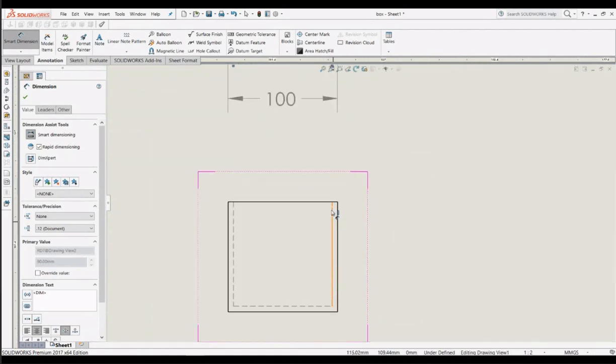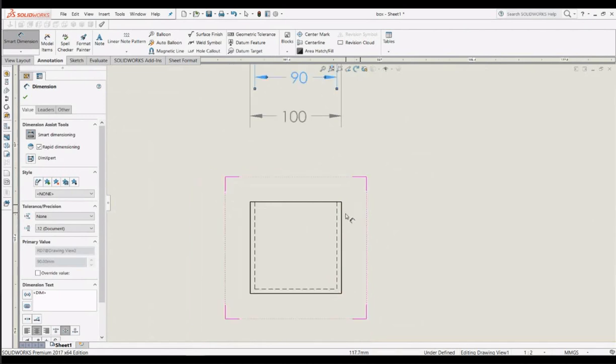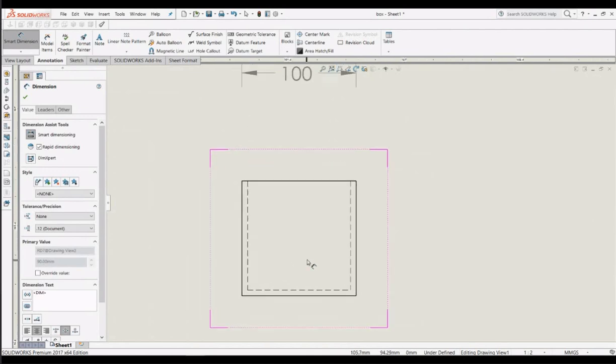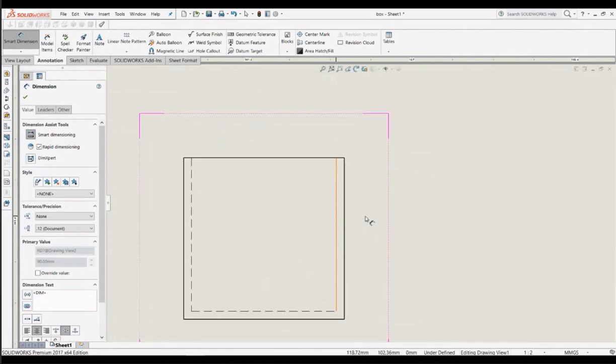Okay, in the front view, you can see here that the line is not complete, right? It's like another line is missing, right? But it's not actually. The hidden line means the line inside that we cannot see from the front view. It's actually inside the hollow box here. So inside the hollow box, the top part of the hollow box, there is nothing, right? So there is no line. But for the side part and the bottom part, we have the thickness for the hollow box, right?